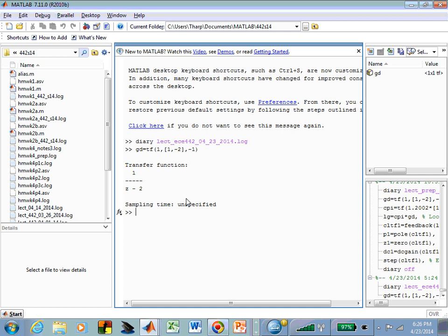There's my plant. Then I'm going to say, okay, here is my third controller design. It's going to be a transfer function, and I don't know what the gain is. So I'm going to find that with MATLAB. So I'm not going to put in a gain, I'm just going to put in a 0. And I already know where those are. I'm going to combine, so I'm going to convolve two first-order polynomials. One of those polynomials is at 0.1, and the other one is at 0.9.